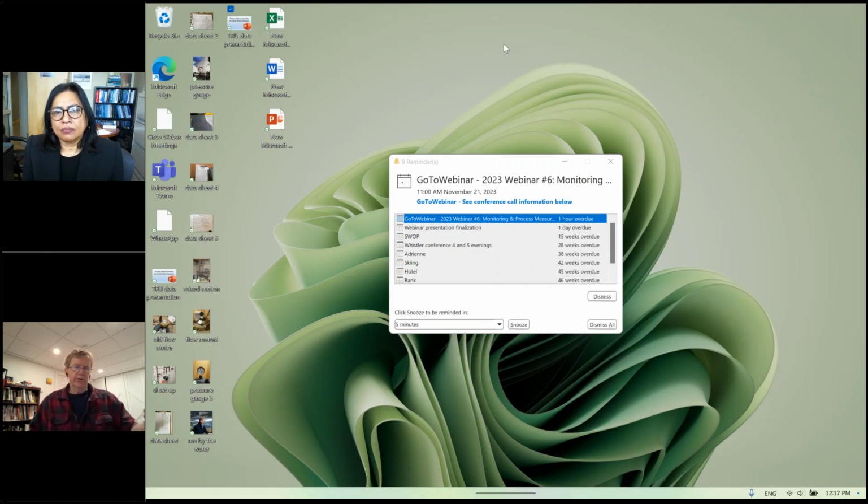It'll tell us the pressure in our line, pressure that's basically going to be delivered to the houses in the area. But then we put on a special pressure meter with a cone, and we blow water out of it. And that'll tell us what our dynamic pressure is, as opposed to the original static pressure. And that should be a particular ratio to the static pressure. And it was significantly lower than we expected. So we knew there was something going on, but of course, that kink was buried in the ground, so we didn't know what it was.